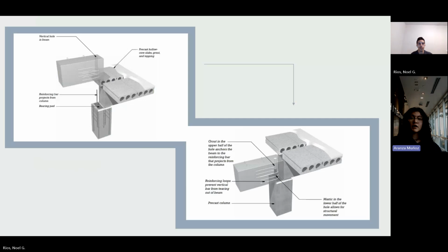In this next slide, more information is provided on precast concrete framing systems. Here, top hollow core roof slabs are supported on beams and are joined to a column with vertical rods. Something similar can also be used for floor beams that rest on corbels.